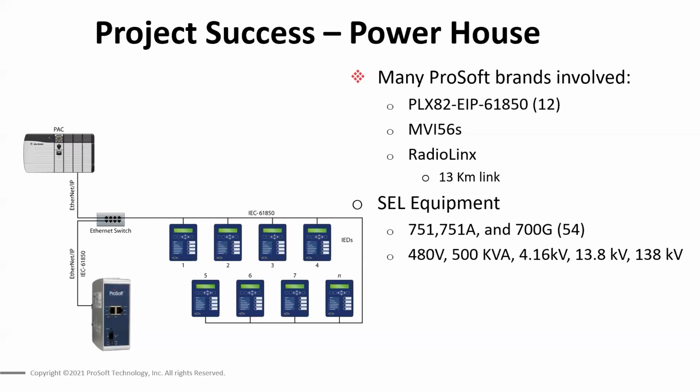The next question is, will the module support redundancy? Yes, it will. At first release, we do not have redundancy built into the 61850 network, but we will be looking at adding redundancy on the 61850 network. As of right now, it just supports the parallel redundancy protocol.